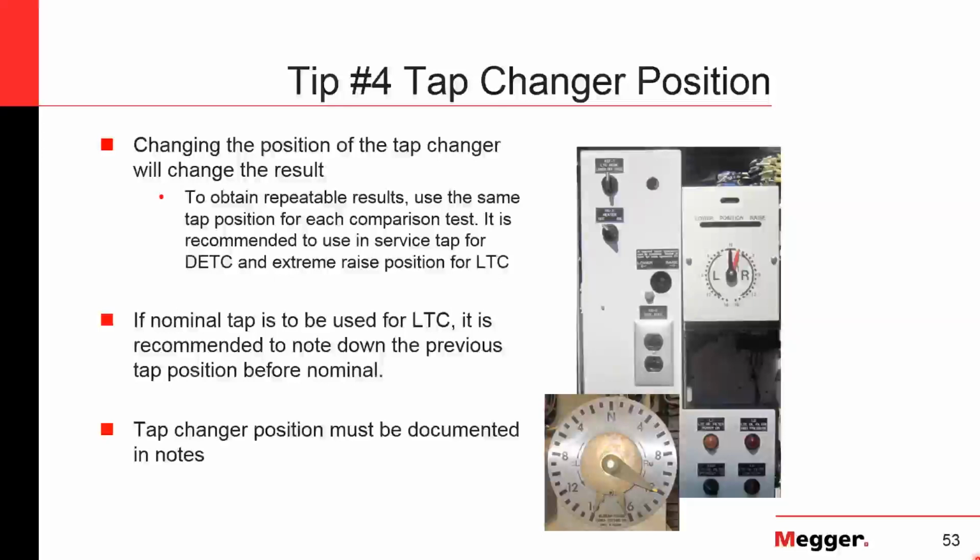Of course, we have different examples of a hoop buckling or a winding collapse or stretching or whatever. But generally if something happened to that winding, it's not just one effect. It might have buckled a little and expanded, the insulation's breaking down, but you're getting an indication that something's wrong with the winding.